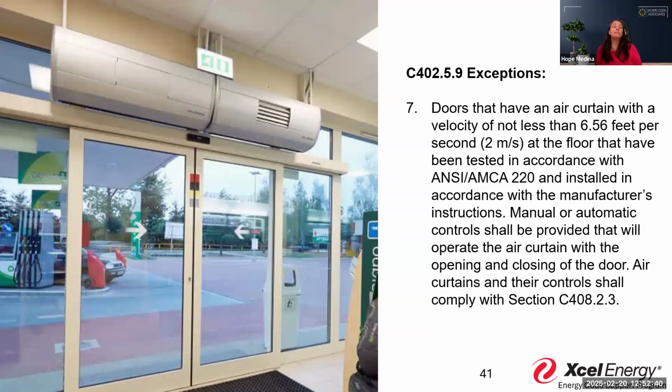And the idea was that air curtains could be installed in lieu of a vestibule for those existing buildings, because sometimes you might not have the configuration to be able to add a vestibule once you start talking about all the requirements. Because a vestibule, while the energy code does not necessarily state how large a vestibule has to be, the building code and accessibility code does talk about doors in succession.